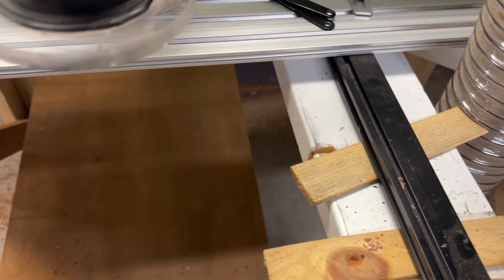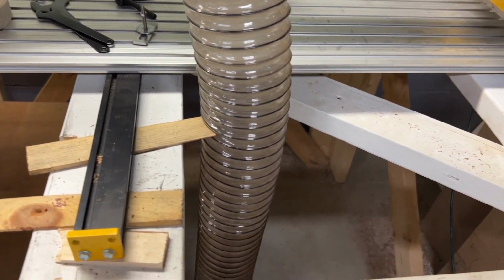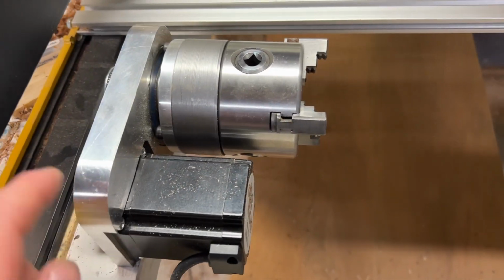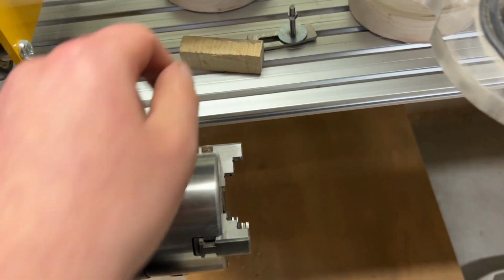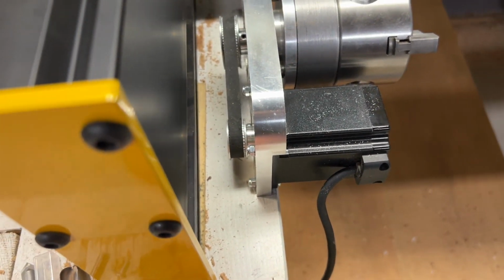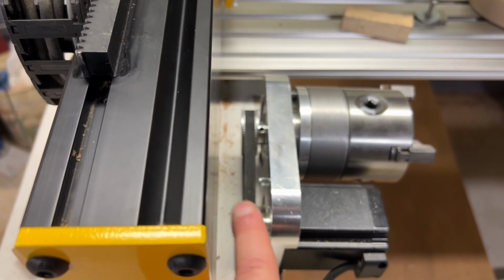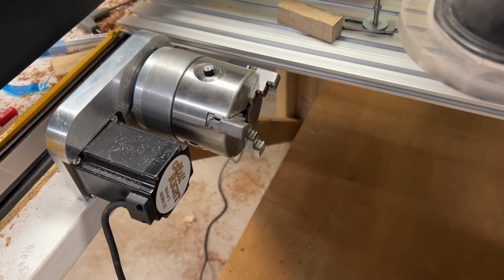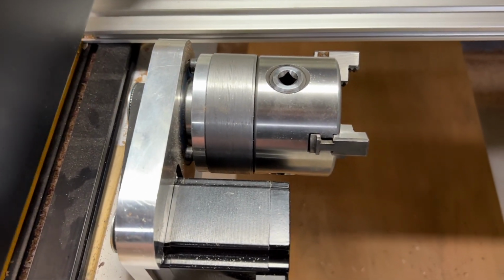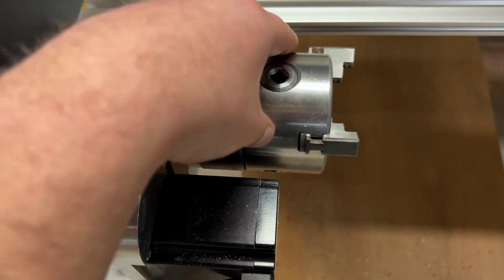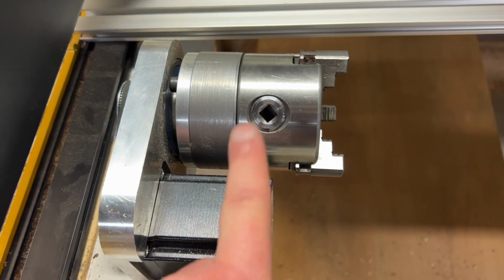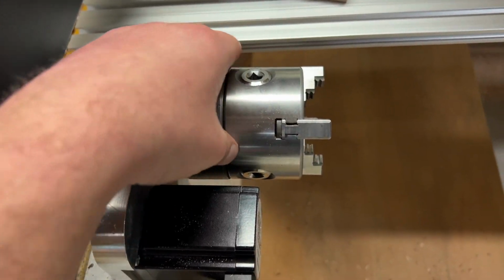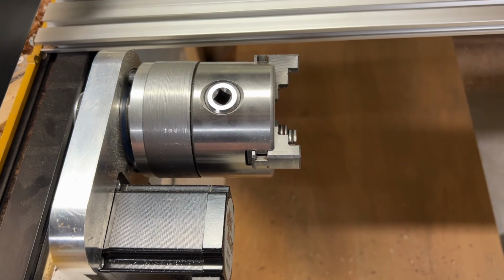I built this table so I could take the aluminum bed out and still have access to the bottom. And I tore this all apart. It comes with a mount for on the bed, but I wanted it on the table. So I trued it up between the two, drilled some holes in the table, and bolted it fast. I also couldn't turn big enough pieces with how it was. These chuck jaws kept hitting off of here, so I turned this spacer. So now I can do large items.